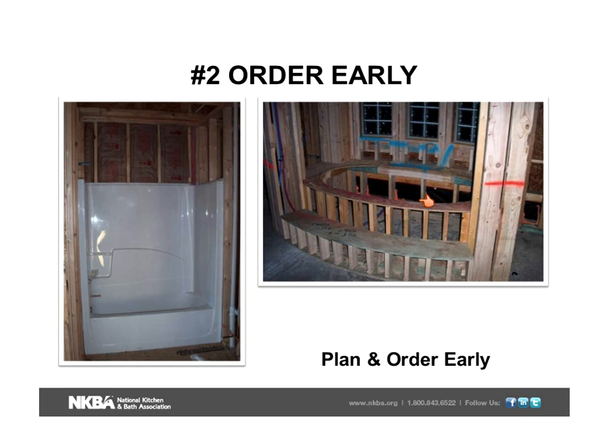So basically with this high bathtub, it'll be much easier for the consumer to sit on the edge at this level and swing their feet into the bathtub. So that's why it's not recommended, and we like to see a grab bar in the final installation. But this is certainly acceptable, and I think probably the reason for it justifies then that rise. But it would be difficult for the person to step on this level directly into that bathtub.